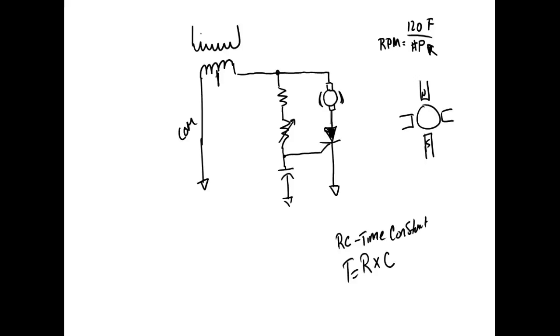And this is why, if you've got a ceiling fan, that's what you're doing when you're flipping that switch. If you look it up, it's got 4 wires, 3 wires coming out, and what are you doing? Well, every time you switch it, you're changing the number of what? Poles. And that's the way they work. And a lot of motors work like that. The motor in your air conditioner is usually a 3-speed motor, and what they're doing is changing the number of poles. But the speeds would be set.